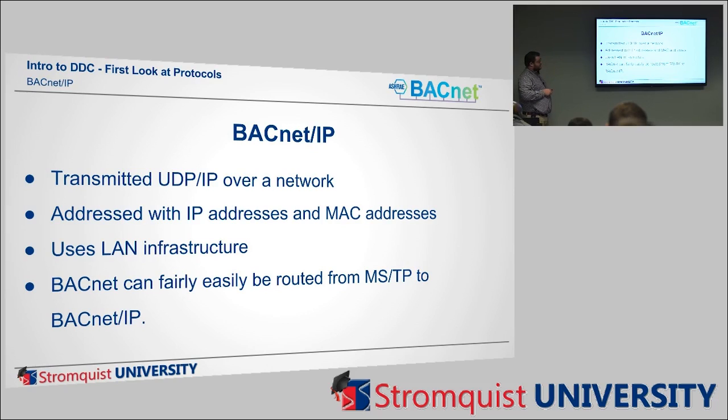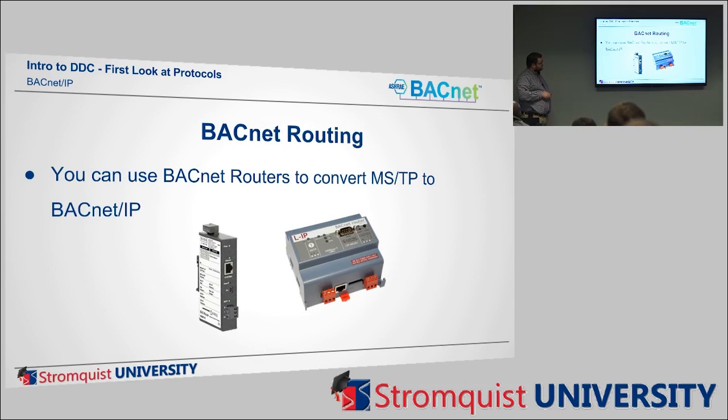And BACnet is a lot easier to route and get from an MSTP up to an IP level protocol. It's a lot easier to do it with BACnet. BACnet routing, you use routers like these, and that converts it from that 2-wire bus to Ethernet to do the scenario where, like, if you have a small outbuilding with 5 thermostats or something like that in it.